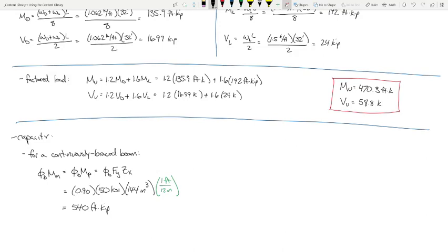So 0.871 is its efficiency. I'm going to introduce you to some terminology. In the land of bridge engineering, we would call that a performance ratio. So the performance ratio under bending is 0.871. It's the same thing. So is this an efficient beam? It's not bad. Remember, we're going to go to a group and select the lightest beam anyway, so there's going to be some conservatism in that, okay?